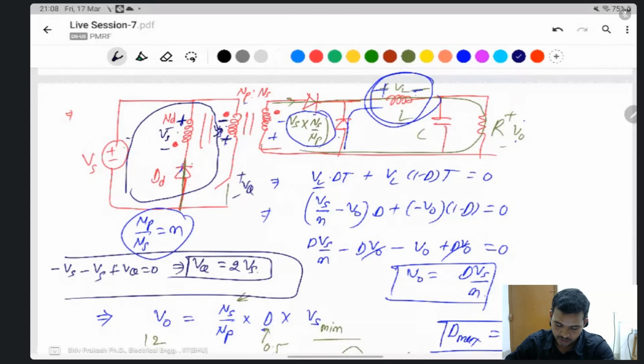Sir, actually, across the inductor when we are switching, there will be a spike in the voltage, right? Some small spike will be there. Yes, these depend on the leakage inductance. Here I will not consider the leakage inductance. If you have a leakage inductance, then the spike comes. But in the ideal condition, I have taken all of this without it.